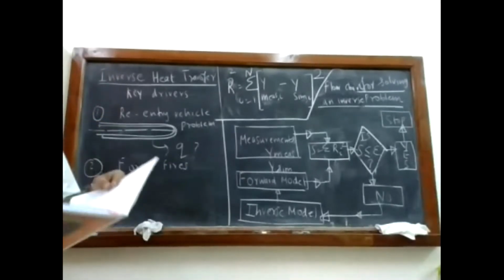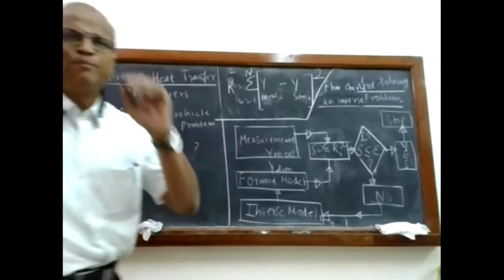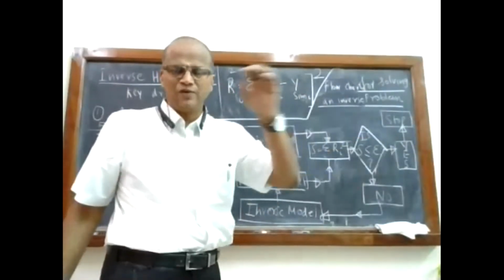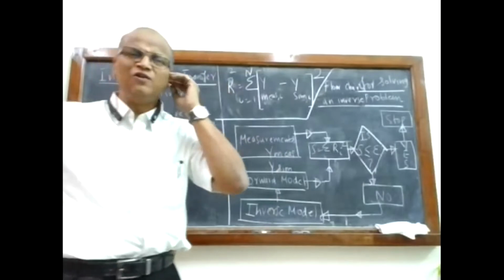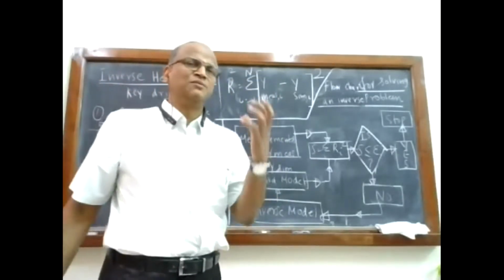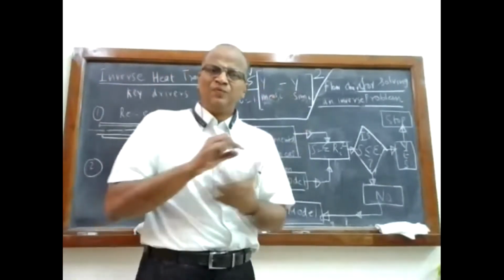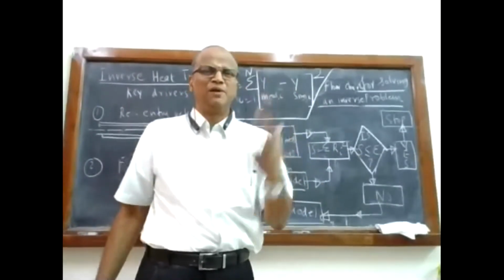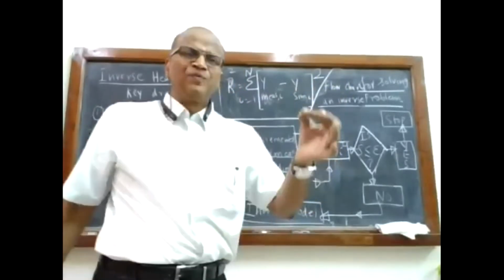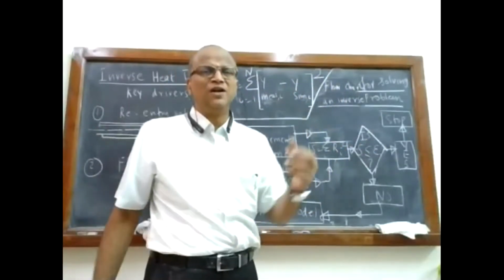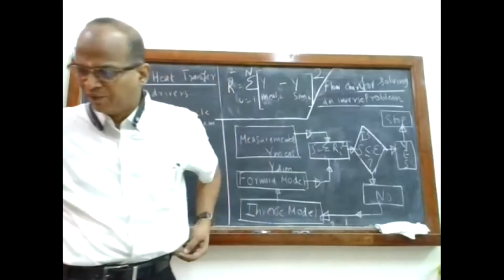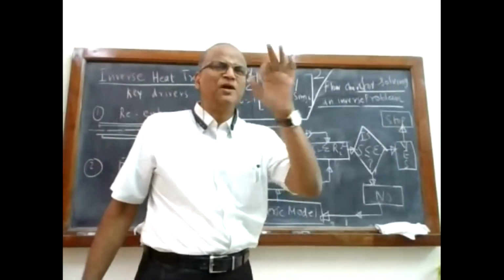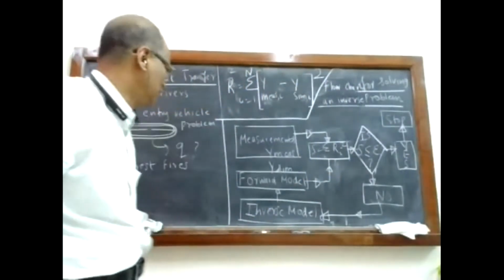If you look at forest fires, the direct measurement of heat flux is gone here. You cannot just put a heat flux gauge into a forest fire, so you should have some scientific way of getting infrared thermograms or satellite imagery, a change in some brightness, some intensity, some other parameter, just like the volume of the mercury changes in a mercury-in-glass thermometer. Some funda you have to use. So detection of forest fire can be eminently done if you use an inverse heat transfer approach.